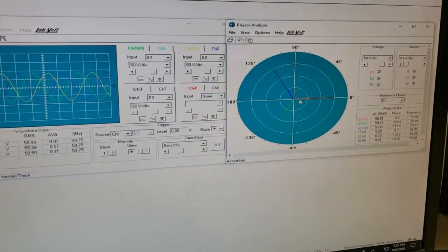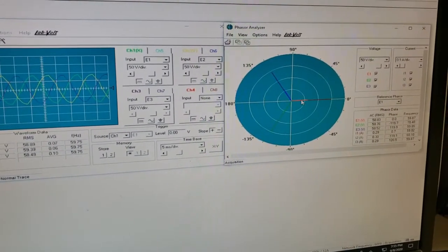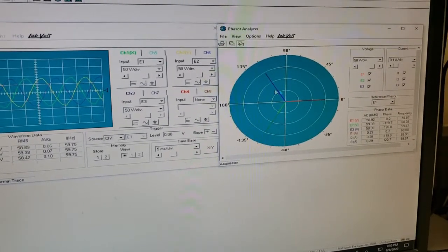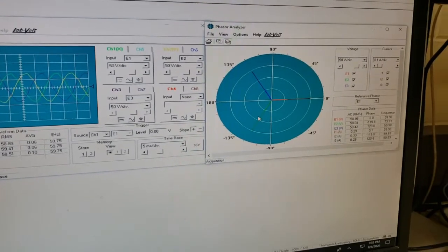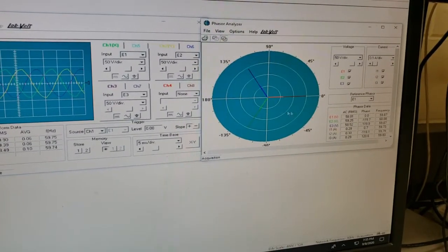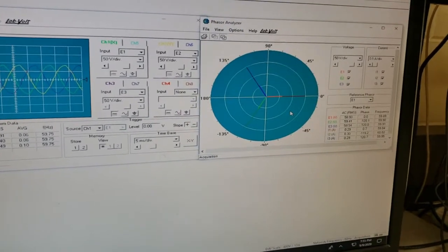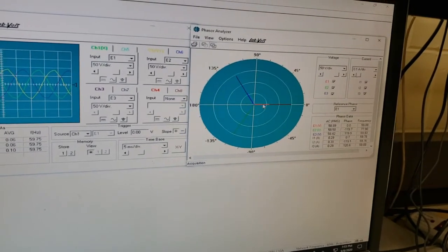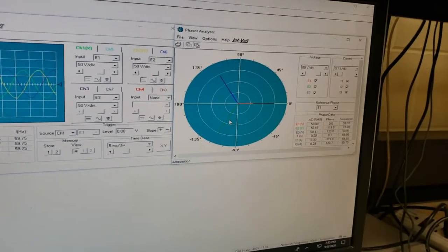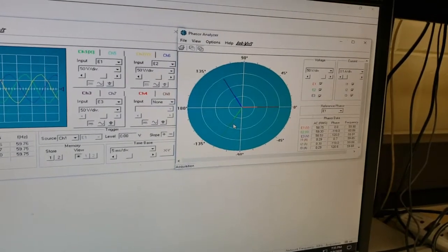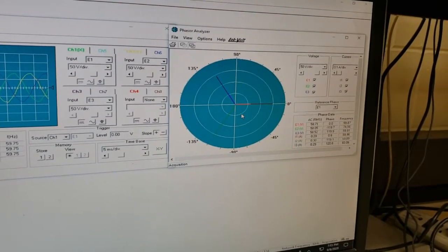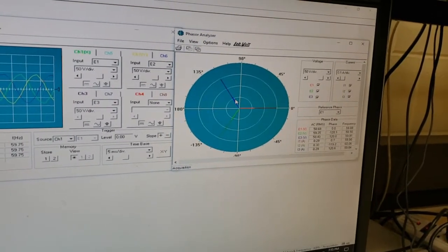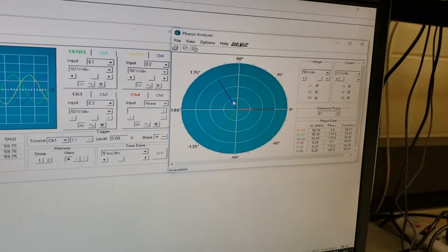You can see the 120 degrees out of phase with each other, and I also drew the longer lines. You see, this is a light red line. This is a dark red line. The darker lines are the currents, and because the loads are balanced, the currents are also three-phase, which is an important note to keep in mind. Currents are not necessarily three-phase just because the voltages are. The voltages will be three-phase because that's the nature of the generation of that power. When you learn about generators, you'll see how three-phase voltage sources are generated. So the voltage will usually be three-phase, but the currents are not necessarily that, because the currents will depend on whatever load is attached to each line.